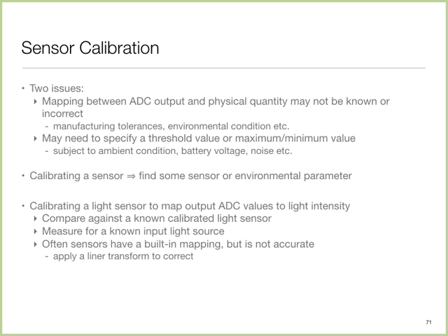Likewise, cameras. When you take a totally dark image, like taking the camera into a dark room, the picture you get is very noisy and grainy. But the noise pattern in that is very unique to the particular camera, the particular imager. Likewise, radios have unique fingerprints. A lot of papers have emerged which use this as a way to break privacy by linking things back.